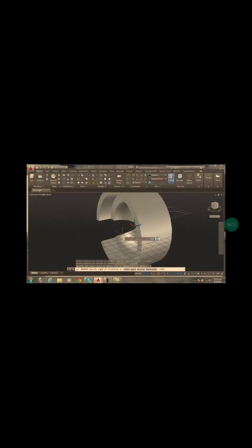Now, if we do the revolve command, I select the revolve command. Select the extrusions, crossing all those, and I hit enter. Down on the command line, I have these various options. I can specify the axis. I'm going to specify the axis as this green line, so it's the y-axis. I'll click on the y-axis, and now it's spinning around that y-axis.